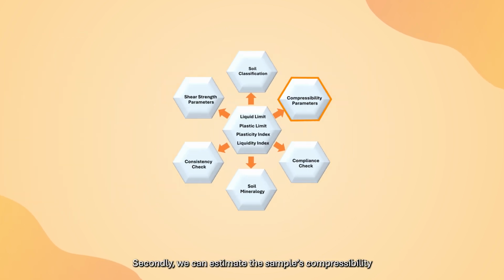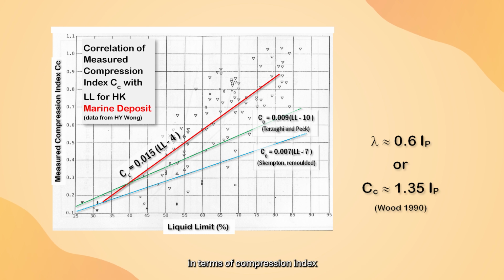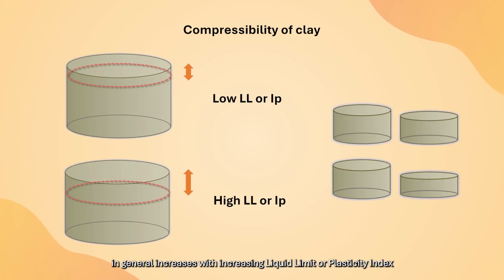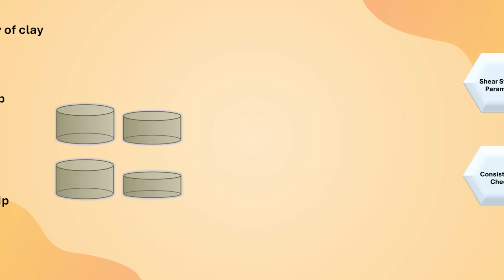Secondly, we can estimate the sample's compressibility in terms of compression index using the liquid limit or plasticity index. The compressibility of a clay in general increases with increasing liquid limit or plasticity index.